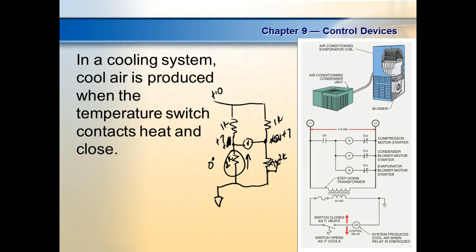So like I said, if you have 7 volts on both sides, there's no current flow through that center thing, and it doesn't mean anything. So normally when we use sensors that vary their resistance, and we need to set a 0 reference, we'll set it up in what we call a Wheatstone bridge. And that way it gives me the ability to do what? Set 0. So what I would do is I would take this sensor, I would put it in a glass of ice water, and I would adjust this till my meter measures 0.